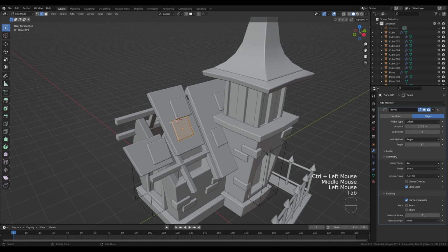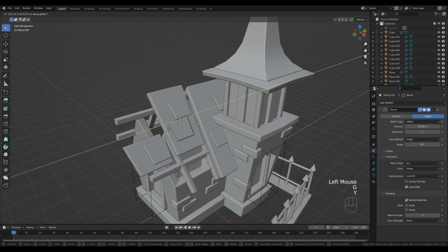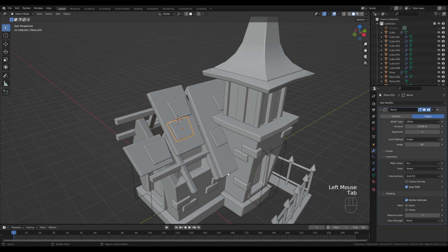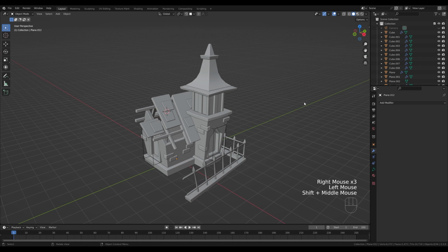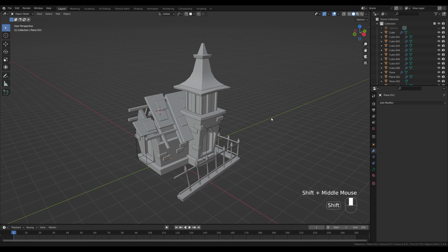And now we can play with the shape of these shingles a little bit, so it's a little bit more interesting. And here you could see how you can quickly, just by blocking out some basic shape and reusing those by duplicating into a separate geometry, and then slicing them up, reusing, converting to curves, and basically just playing around, building up from that basic shape that you blocked out, how easy it is to come up with the design in a few minutes like this.